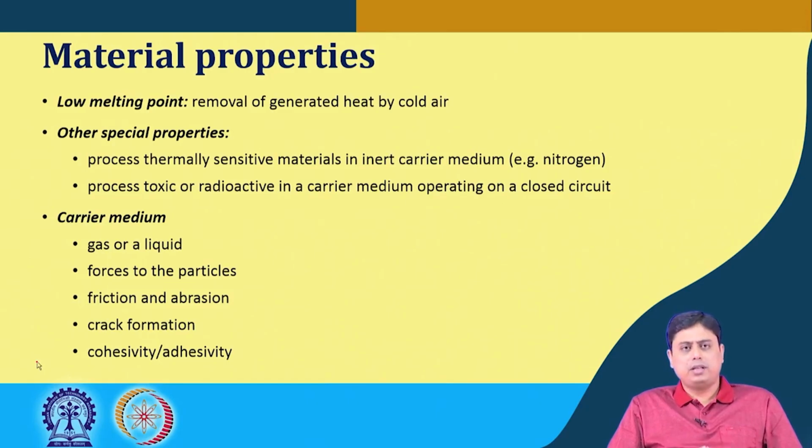Other properties that are sometimes important: if the process is thermally sensitive for the materials, then in the presence of an inert atmosphere or inert carrier medium, the grinding operation can be carried out, because the material itself is temperature sensitive. So, in the presence of atmospheric air or oxygen, it can create some hazard.